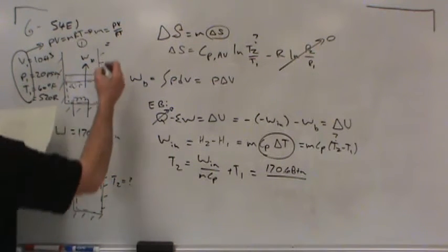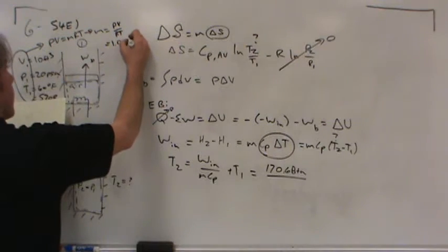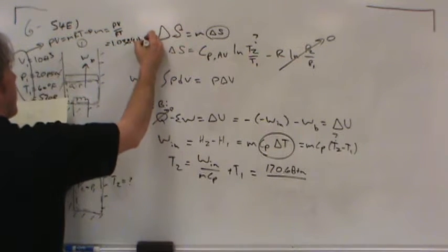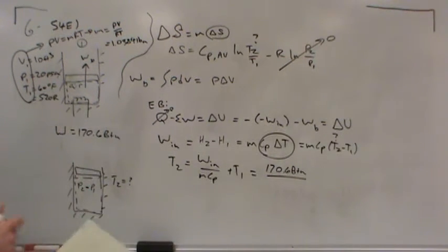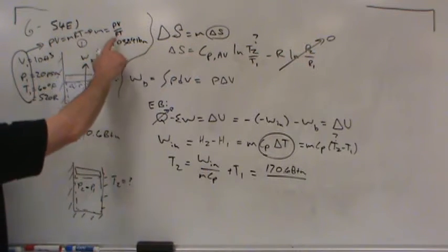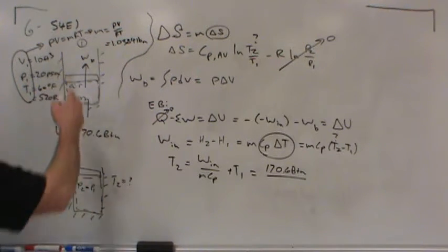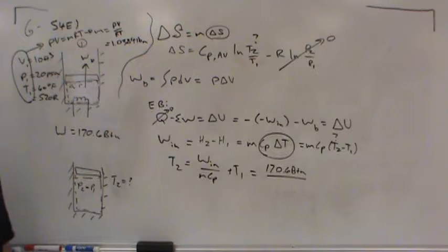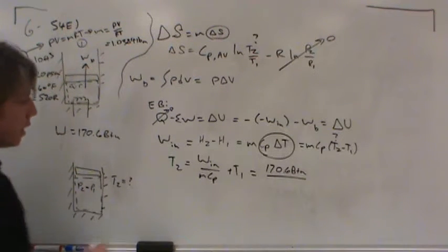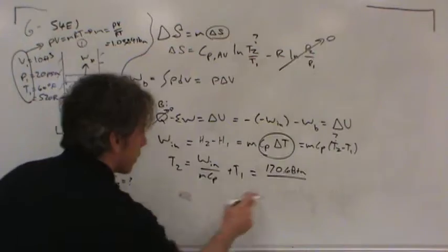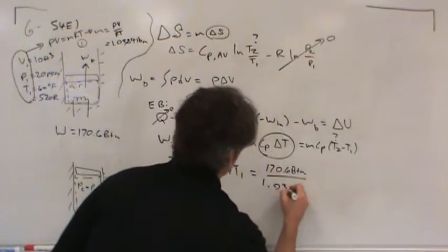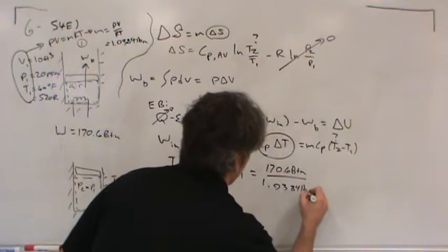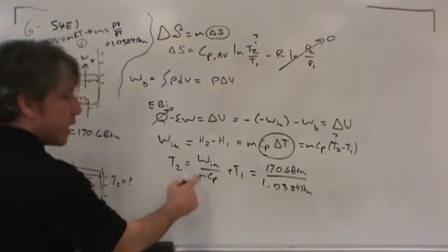there it is. 1.0384 pound mass. Okay? No point in going through the ideal gas law and the details. You'll have to look up the gas constant for air. You plug in PV and T, and there you have it. Okay, so straightforward, simple stuff. Now, we're already working here. So the mass is 1.0384 pound mass. We need the heat capacity of air.